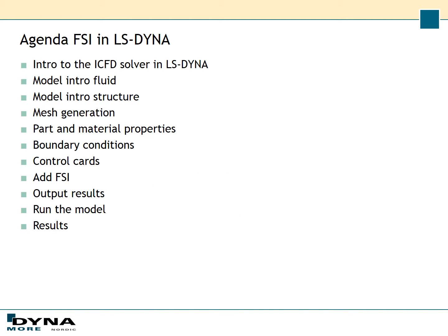First I will give a brief introduction about the ICFD solver, and then we will go into the model intro for the fluid and then a model intro for the structure. Then we're going to take up how to create the mesh and create the necessary keywords for the model to run. And then after we have set up the structural model, we're going to add FSI, and then we're going to run the model and look at the results.